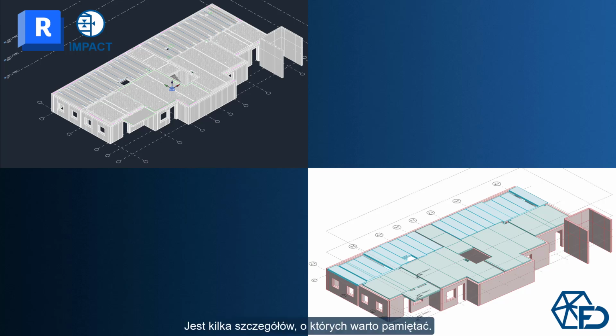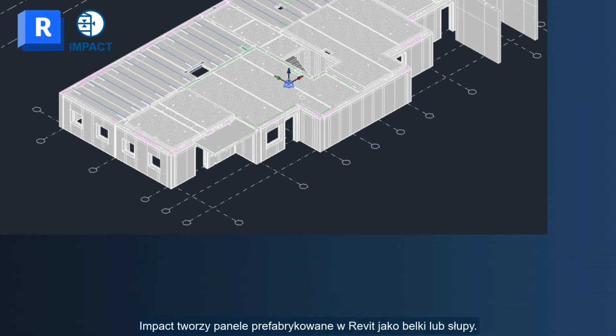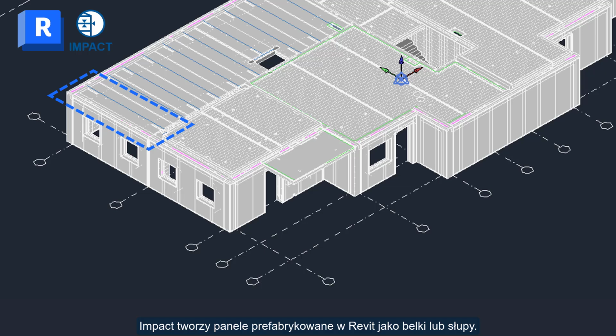There are a few details to keep in mind. Impact creates precast panels in Revit as profile beam or column objects. To transfer them to FEM-Design, we first convert them into analytical members using Revit's analytical automation.